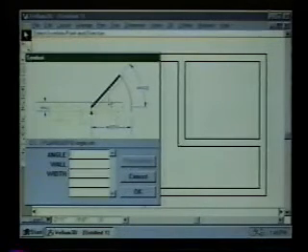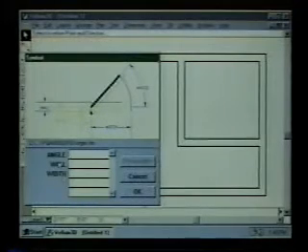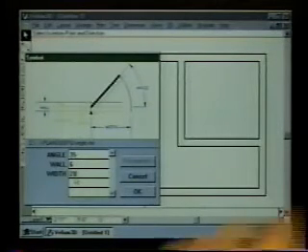So with a single door, I've got every possible variation of this door covered. So I don't need a whole symbol library for this door. All I need is one door. So we'll type in 35 degrees. We know it's a 6-inch wall, and let's put a 28-inch door.